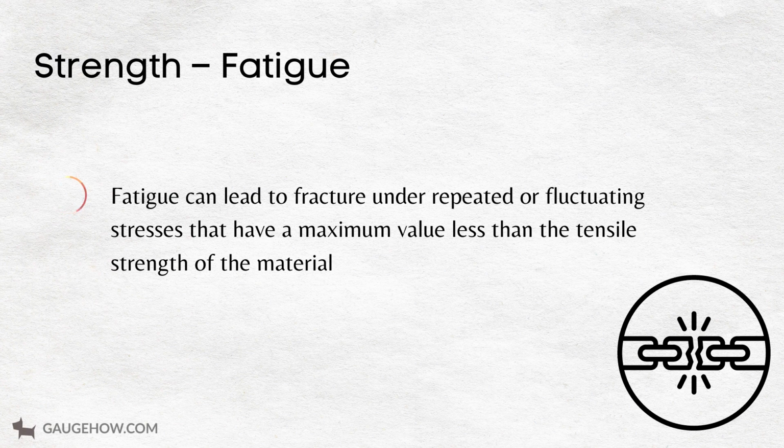Strength, fatigue. Fatigue can lead to fracture under repeated or fluctuating stresses, for example, loading or unloading, that have a maximum value less than the tensile strength of the material. Higher stresses will accelerate the time to failure and vice versa. So there is a relationship between the stress and cycles to failure. Fatigue strength is an important consideration when designing components subjected to repetitive load conditions.